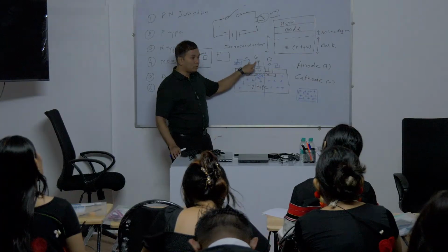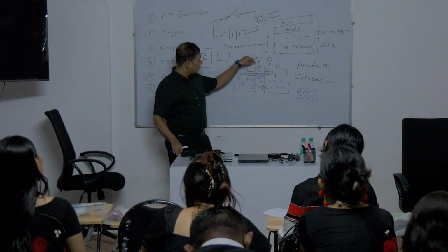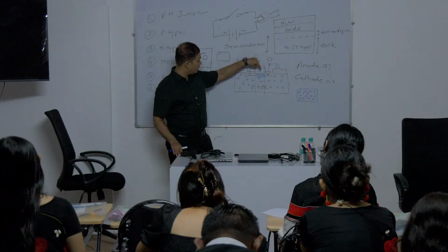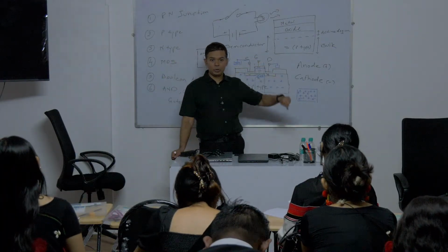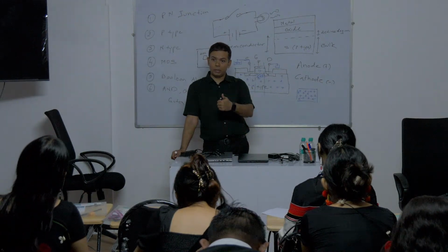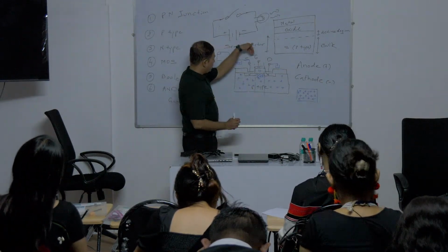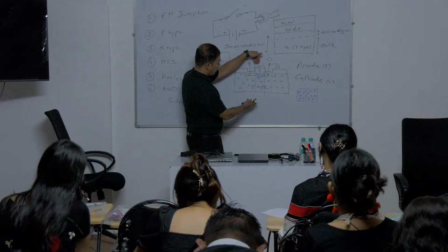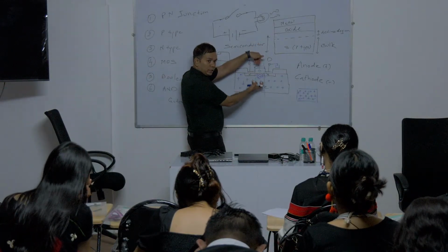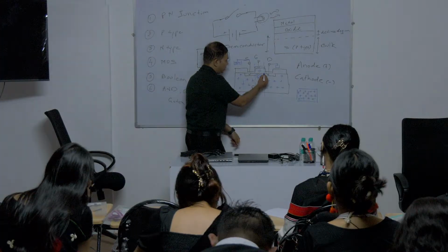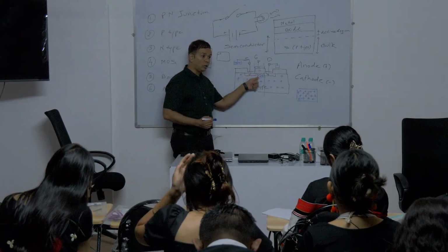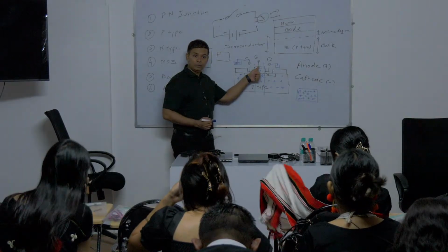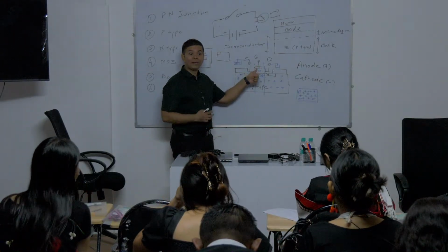So you are giving a positive voltage at the gate. There is a metal layer over here and there is oxide. The oxide layer acts as an insulator, which means it will not allow anything to pass through. So when you apply a positive voltage, all the electrons will be attracted, and the reason it will stop over here is because the insulator will not allow them to pass through, because it is a bad conductor of electricity.